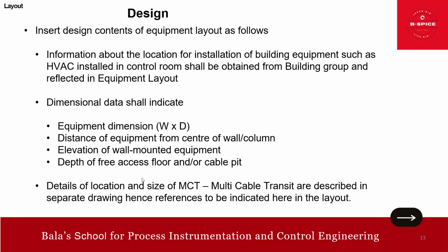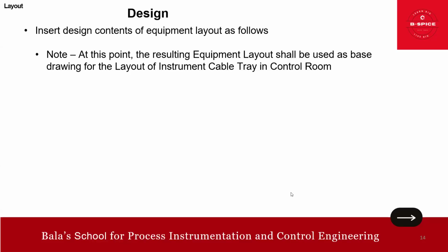Then detail and location of size of the MCT. This is called a multi-cable transit. So that also, of course, will be prepared in a separate drawing. If you are interested, you can comment, I will also talk about this subject. But the point I am saying here is this MCT reference is to be indicated here in the layout. I will show you in the layout later.